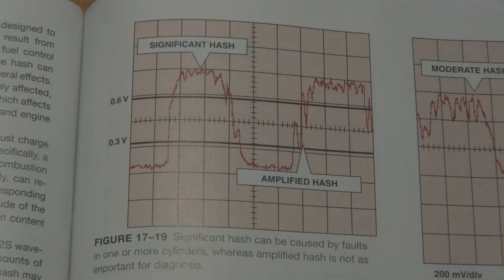A spark plug, a coil pack, or a single fuel injector fault is typically going to cause one cylinder to go down. A fuel pump, on the other hand, is going to cause an entire engine issue. On a vehicle that has two banks, one oxygen sensor going bad is only going to result in one bank having issues.